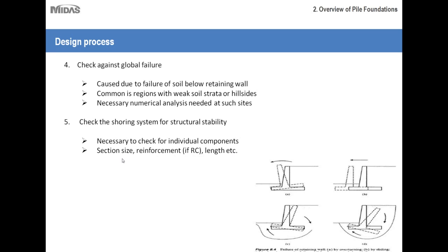So for example, the section size, the reinforcements, and the length, etc. This is something that you can do with a numerical modeling program: you can model your structural elements, and then you can check your moment diagrams, your axial forces, your shear forces, etc. And accurate forces in members are essential for optimal design.